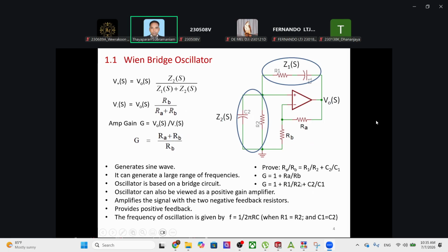What we can do is take 1 kilo ohm for RB and a 1 kilo ohm fixed resistor for RA, plus probably a 2 kilo ohm variable resistor. We cannot choose just 2 kilo ohm because we cannot reduce below 2.